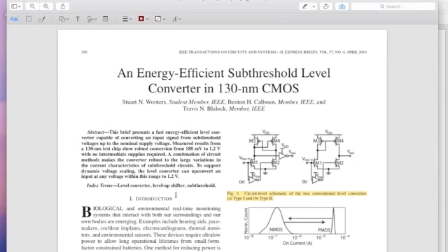So one of the approaches is to get very low power, so that either they run off very small, tiny batteries, or they can run off power harvested from the ambient through solar, or thermocouples, or vibration and so on, so that you don't need to deal with batteries for them. Now, one of the key techniques is to reduce the voltage to very low levels, down to a few hundreds of millivolts. This is near the threshold voltage of the transistor, so that's called near threshold computing. But no matter what, you will have a chip where some blocks are running off higher voltages, especially blocks which are connecting to the outside of the chip.